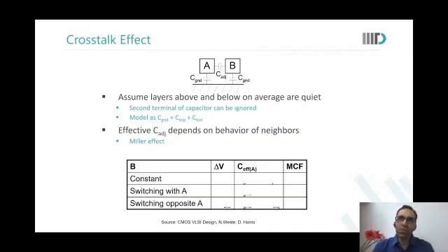So what you can do is say, okay, this capacitance is of very high importance to me. This delay is the longest delay, so I would not want to add any wire delay into it. So you can put comments in your schematic that make the layout of these devices as close to each other as possible, so that when you start to lay them out, you remember that this was an important consideration. But otherwise, you cannot really do much.